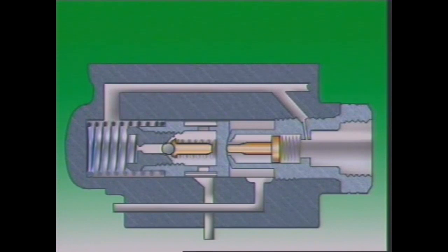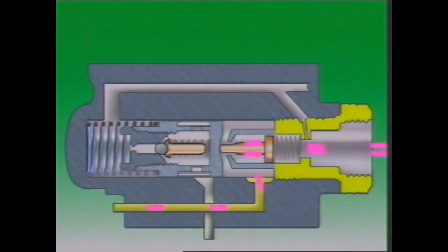During slow cornering or when parking, pump speeds are normally low. There is less demand for fluid flow, but to provide the required assistance, high pressure is needed. Discharge ports direct the fluid to the outlet and then to the steering gear. The outlet fluid pressure is slightly lower than the internal high pressure coming from the pump. This drop in pressure occurs as the fluid flow passes the needle and orifice in the outlet fitting.